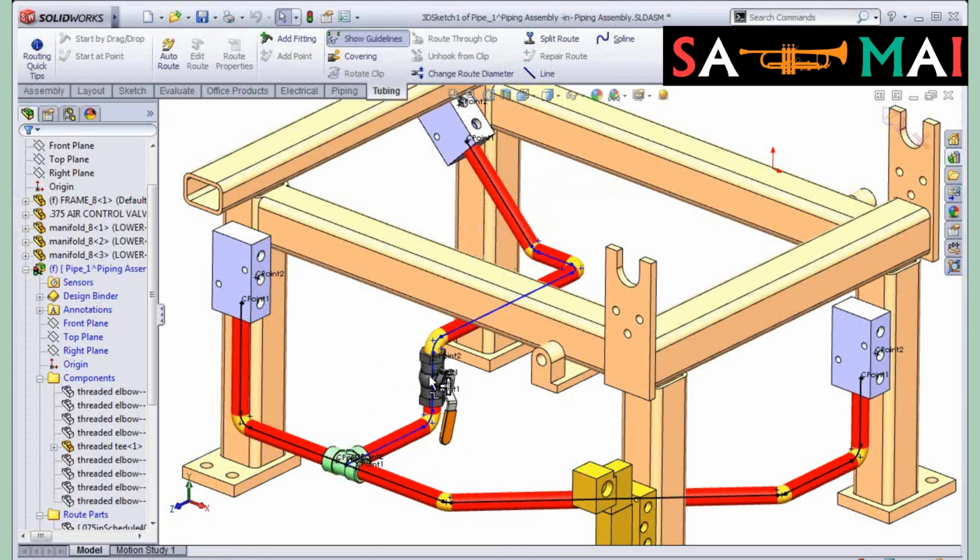Oh, you guys aren't seeing that, are you? Oh, there you go. So wherever I snap it onto a pipe, I want to snap it up here. My tab key then will flip the handle one way or the other way, because there's two possible ways this guy could be mated in there. Either connection point 1 at the top or connection point 1 at the bottom. It's just flipping the valve.